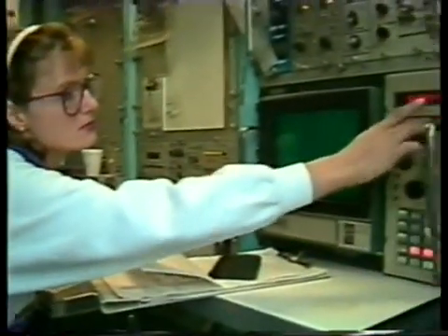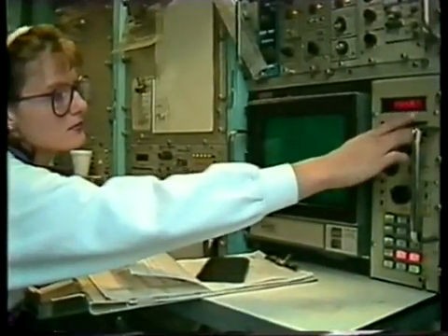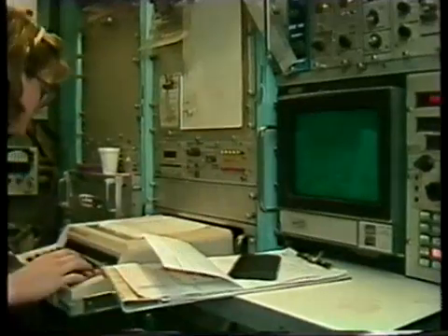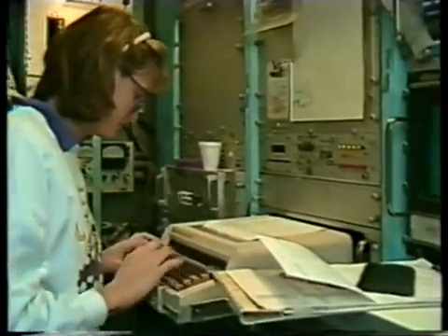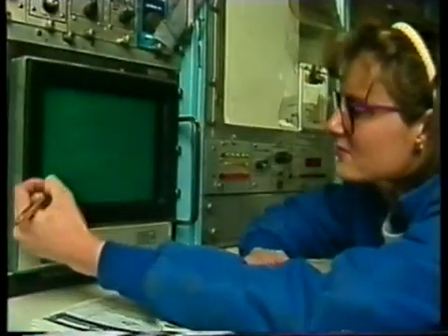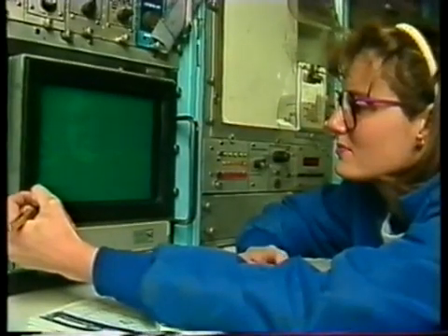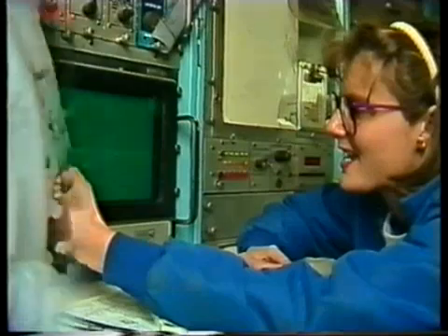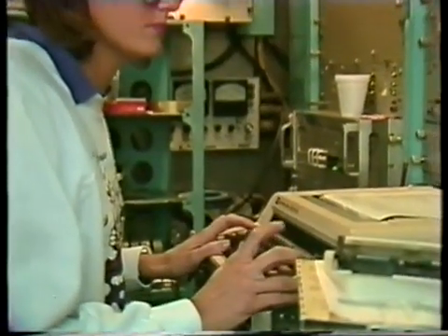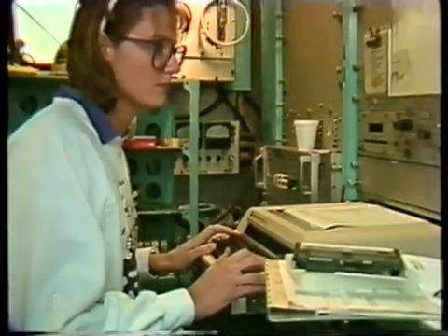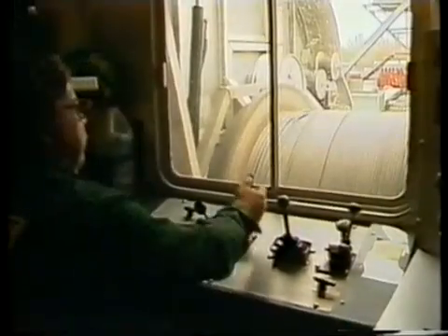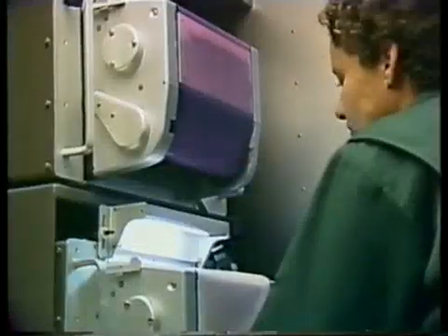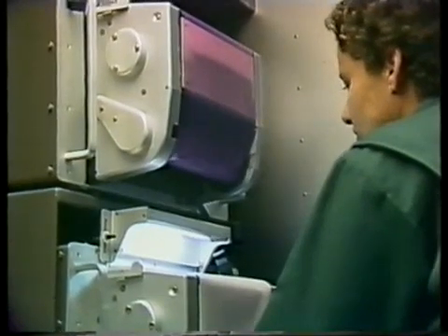For the on-depth check, the logging engineer verifies that proper displacement to one common depth point is valid. This is done by comparing all curves at lithology breaks to determine that they show lithology changes at the same depth. If not, the logging engineer makes any necessary adjustments so that on-depth plotting occurs. After logging the repeat section, the tool is lowered to bottom, and the repeat section log is examined.